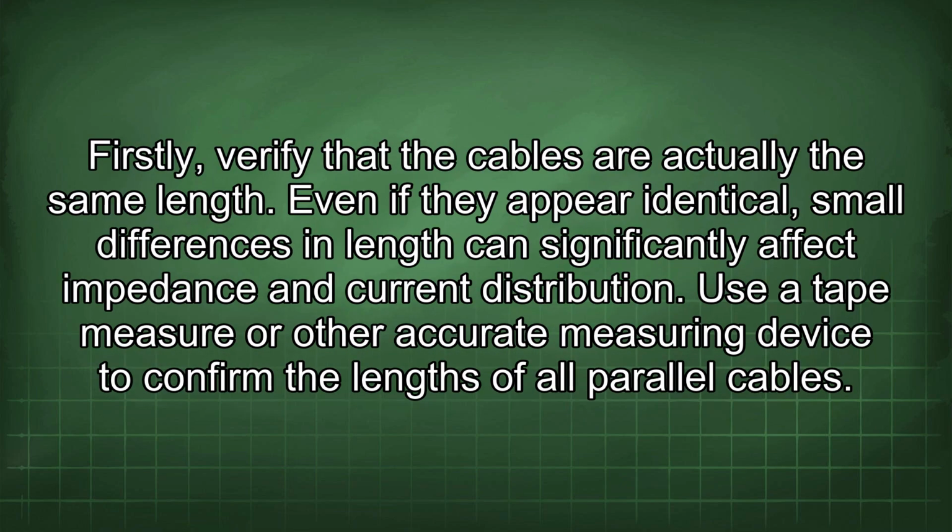Firstly, verify that the cables are actually the same length. Even if they appear identical, small differences in length can significantly affect impedance and current distribution. Use a tape measure or other accurate measuring device to confirm the lengths of all parallel cables.